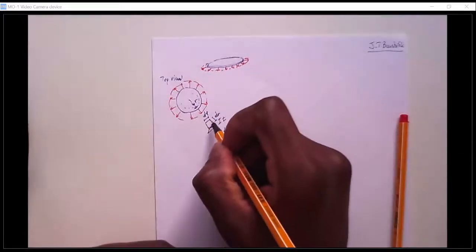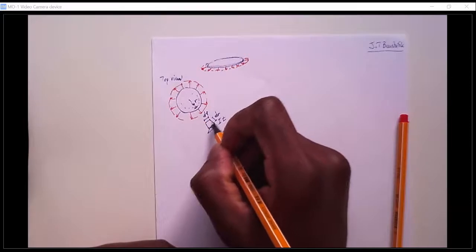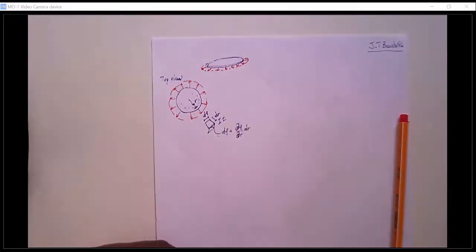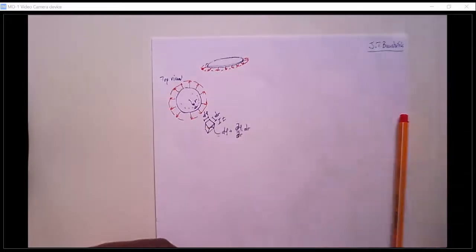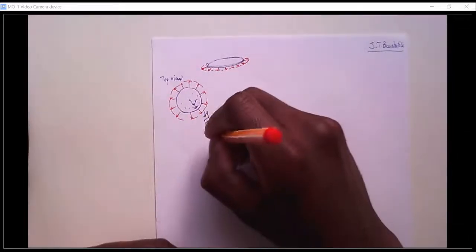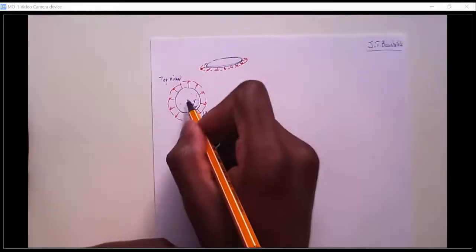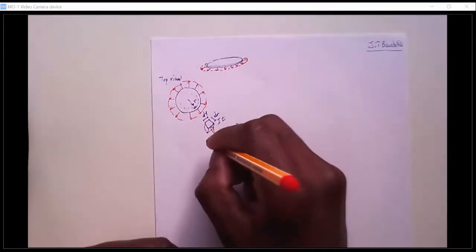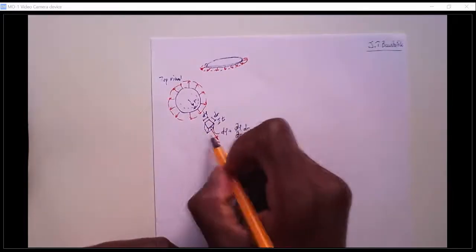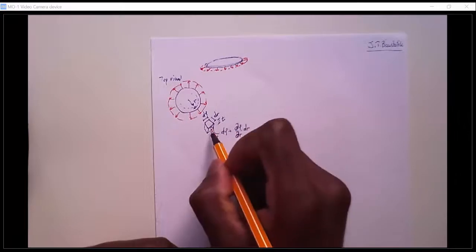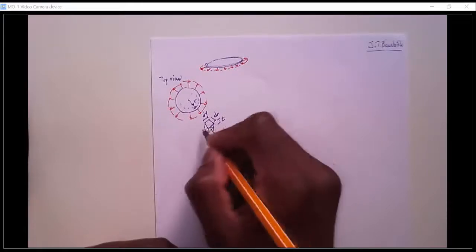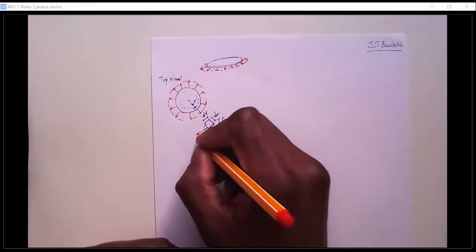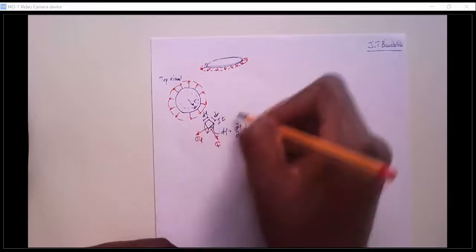And here we can say that the parts here on the left and on the right are equal. It's okay. And the reason why I did all this was to show that the stress in the radial direction would be this one, the stress in the direction of r, in the direction of the radius. I'm just drawing it here with one arrow, not with like a surface load. I hope it's fine. And the circumferential stress is perpendicular to it, in the direction perpendicular to it, it would be this one. So this would be our sigma phi. It's in the circumferential direction.